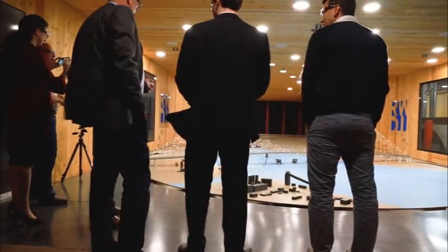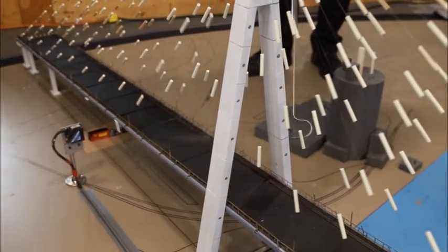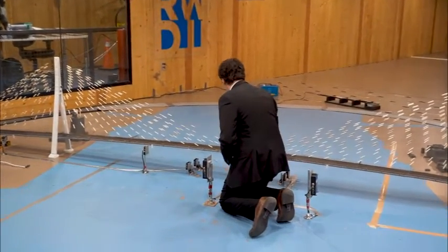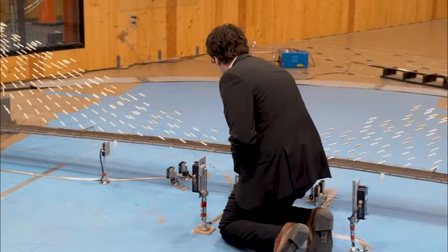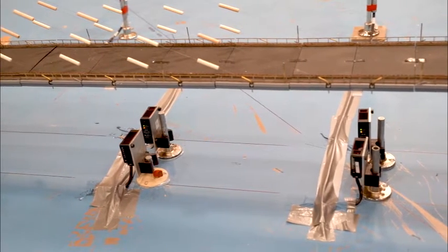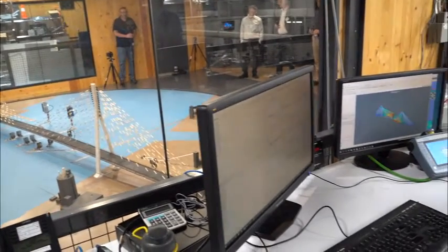For major long span bridges, wind tunnel testing is one of the few items that we still have to do by an experimental method. Computer programs are just not far enough advanced where we can do a computational analysis of wind on a structure. The bridge has to be assessed both for its completed configuration and also for the construction, to ensure that we have a stable bridge while they're constructing and also in the completed project.